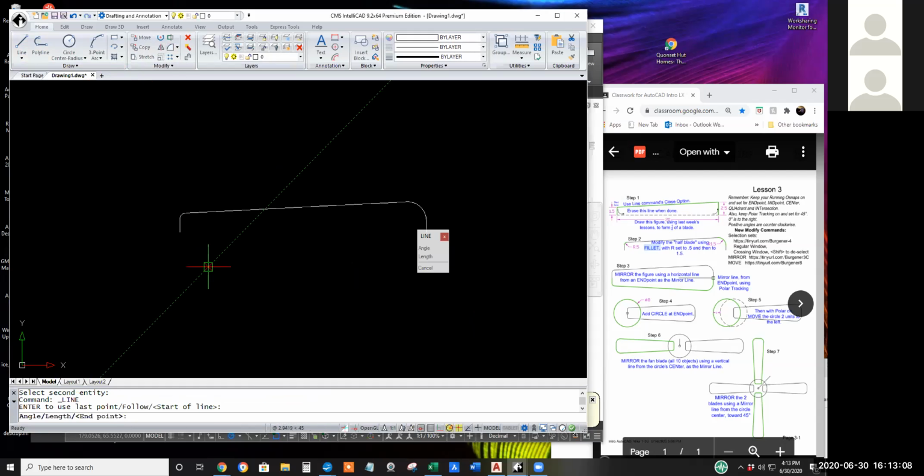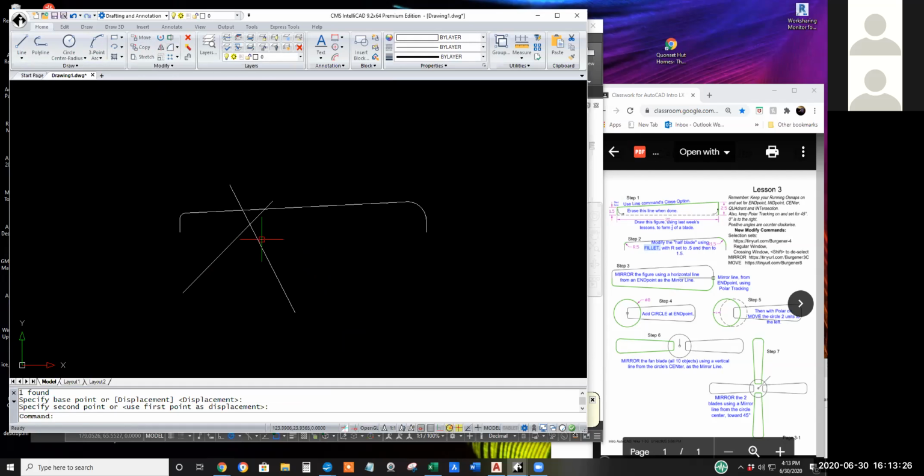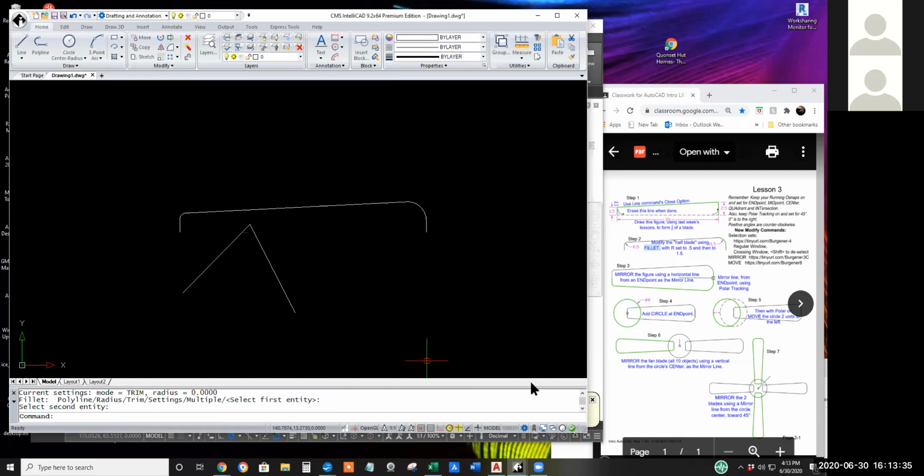And similarly, if you've got two lines, you can fillet them at a 0 unit radius to make them intersect. Move one. In this case, the lines are too long. I can fillet them down to an intersection. AutoCAD will lengthen or truncate by default. You can rig it so it does not change the lines, but I don't know a reason to.